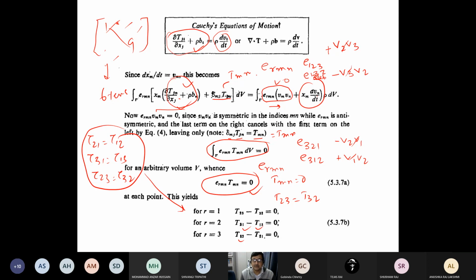So Newton's law, Hooke's law, whatever you enforce, is on the deviatoric stress rather than the thermodynamic pressure. Pressure is an eigenvalue, an invariant; it comes out of the Cauchy stress. It is the part which doesn't change with the change in the frame. Correct? Any question up to this point?